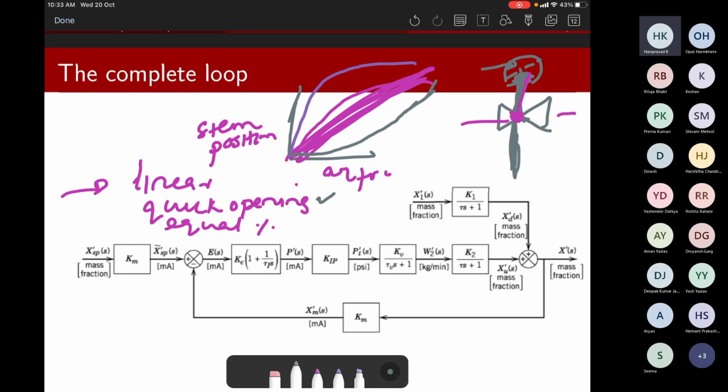Because if for instance you're adding a chemical or a chemical line, excess of that makes your overall process and product quality deteriorate, then you will have to operate in a very careful fashion. Every opening it would only open up a little bit, so you have more control.